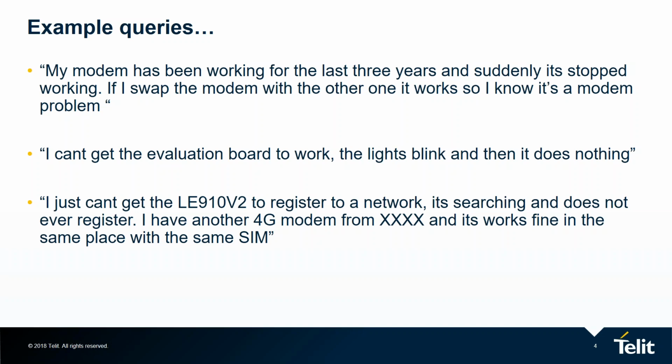So of course we'd been through everything, installing the new drivers, etc. And it seemed for him, not even trying another PC, many of the last cases worked, anything I could think of. So in the end, I ended up driving there and having a look, and on the table, what do we see? Immediately it's obvious. The USB was connected with a set of flying wires, curled around, loose, across a couple of feet of rat's nest of evaluation boards, a real electrical mess.